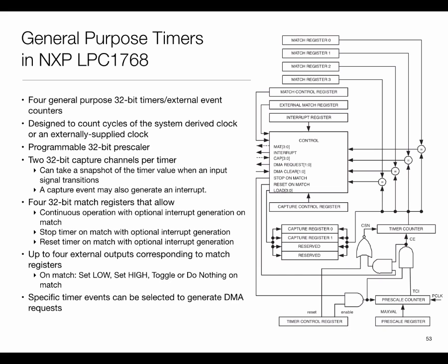Then there are also these notions of what are called match registers. And the idea out here is that I will let my counters, my timers count up, but when they hit a particular value, I want something to happen. So this is how I can create interrupts at arbitrary times, sleep until a particular time. So my counters can free run, but whenever their value matches a particular value, then an interrupt is generated.